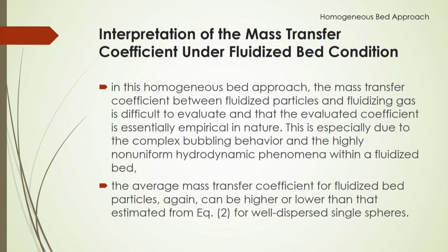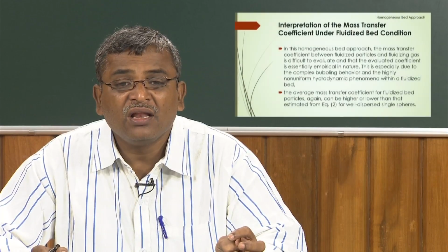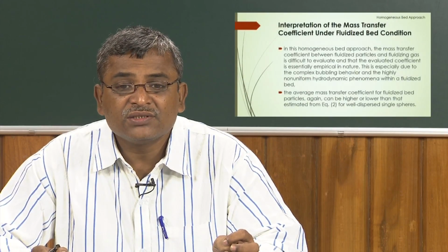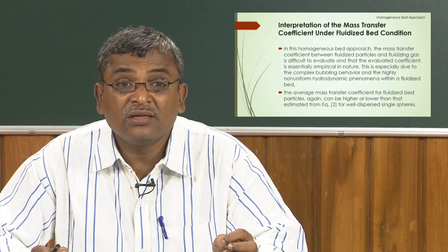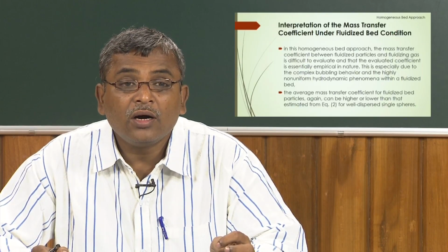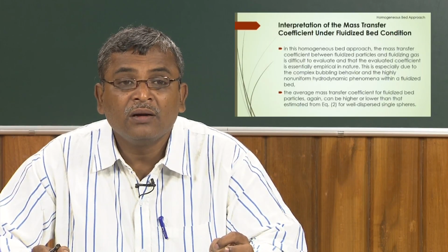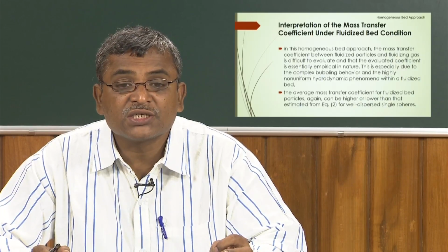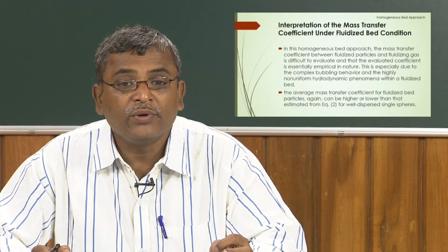Now, in this homogeneous fluidized bed approach, the mass transfer coefficient between fluidized particles and fluidizing gas is very difficult to evaluate, and the evaluated coefficient is essentially empirical in nature. This is because there are several operating conditions that affect the mass transfer phenomena inside the fluidized bed.